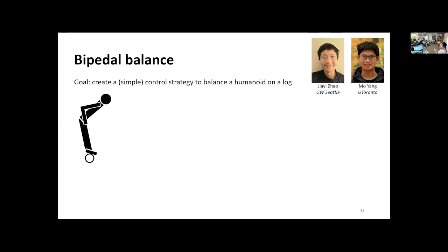Okay, so let me say this. The assumption is that you cannot slip off the log, so you have enough friction that all you're doing is this on the log with your foot, and then we allow it to move both the ankle and the hip joints. This is because if you use a single inverted pendulum model and you only allow it to move the ankle, then you basically can't balance that well. You can only balance well if no one's poking you. So we wanted to be able to balance if someone pokes us. So that's why we have to add that.